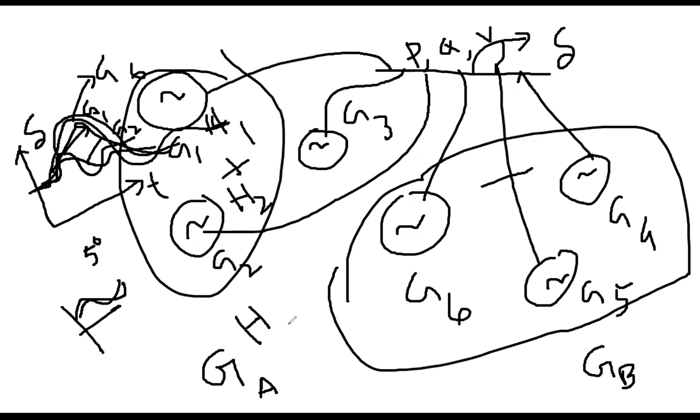By assuming that, you calculate the power flow and everything, and it will be very, very close to the original system. This means the concept of coherency, or making coherent groups, will reduce your computational burden, and its characteristics are very close to the original system.